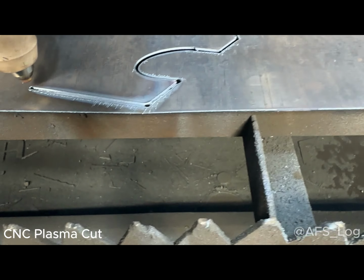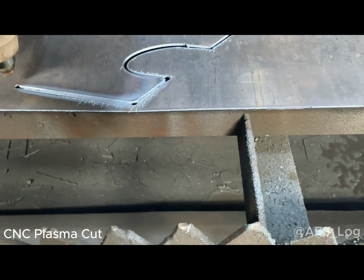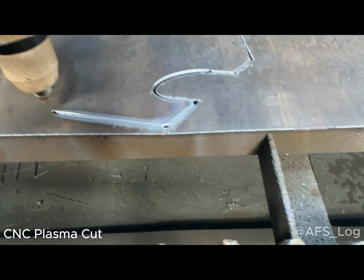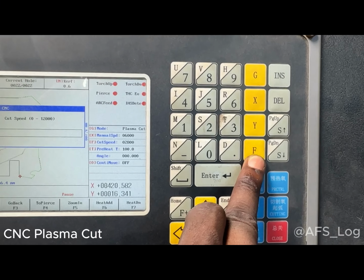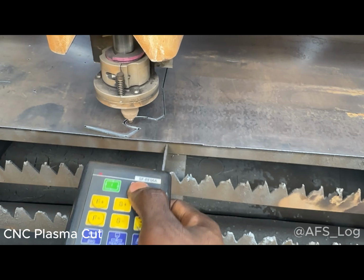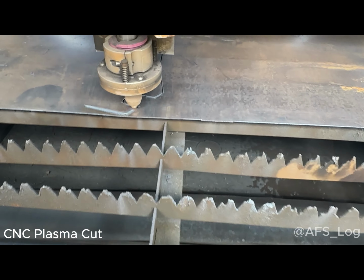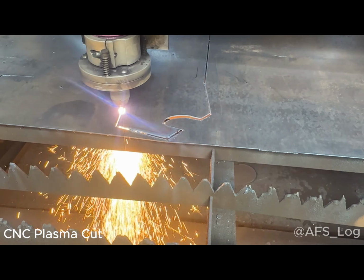Now, look at this. It is wrong. That's what you get when the nozzle is weak, the plasma is weak, and you have too much speed. So I come here and reduce the speed from 2800 to 2500. Then backward. Alright, you can start from here, and I resume from there.